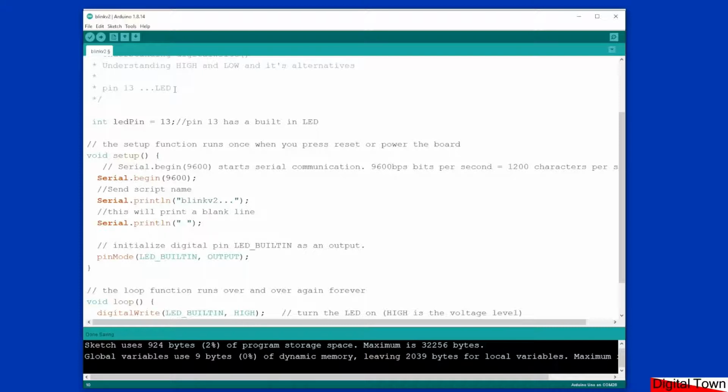Now you might think, crumbs, there's only 12 pins. How difficult can it be? Well, if we were using an Arduino Mega, that has 54 digital pins. If you're starting to use that many pins, and I've done projects where I'm well over 40 pins, you cannot remember what is on every pin and whether you've used a particular pin. So by keeping a list in the header, you know which pins you've used and which pins are still available.